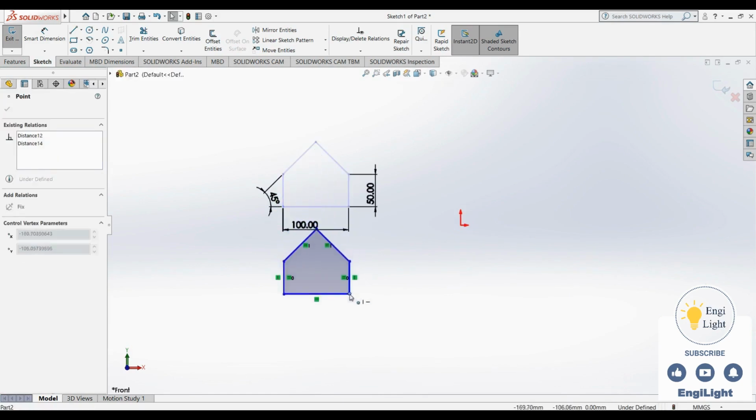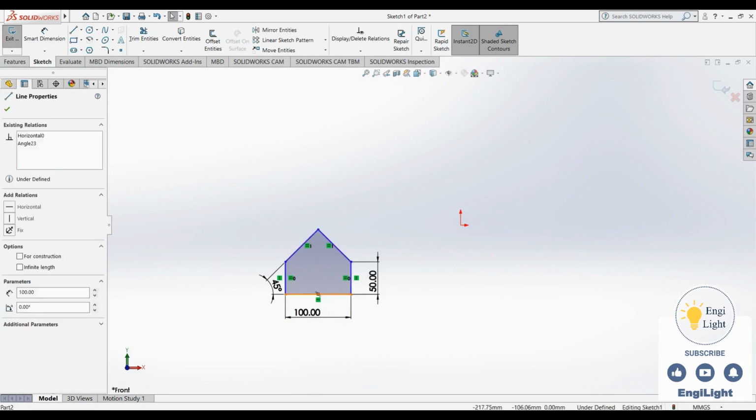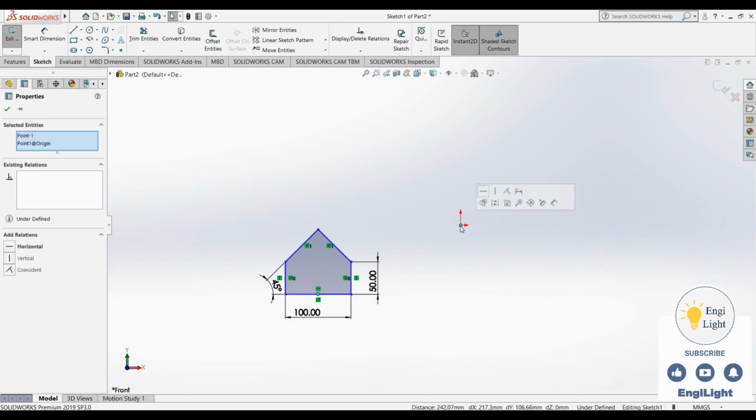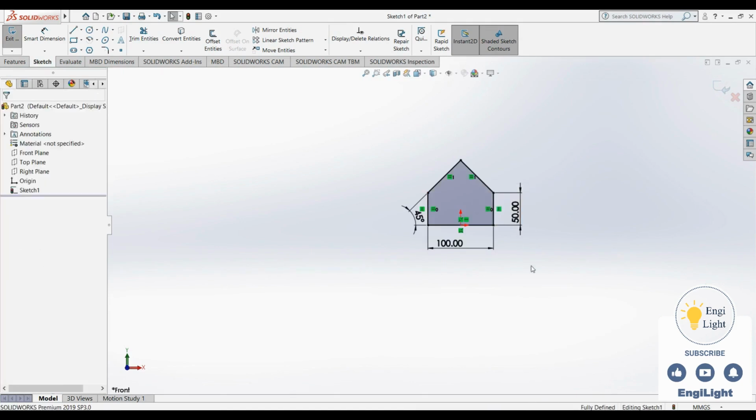This time, we're using a different approach. SolidWorks shows us the midpoints of line segments. When you hover over the line, the yellow point that appears highlights the midpoint of the line segment. Or, for this line segment, this yellow point is at the midpoint. I select this point, hold Control, select this point as well, and then choose the coincident relation. Now, we can see that, much easier, our origin is positioned here, and the sketch is fully defined.